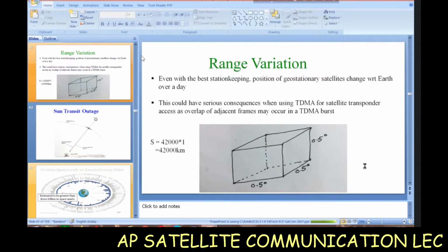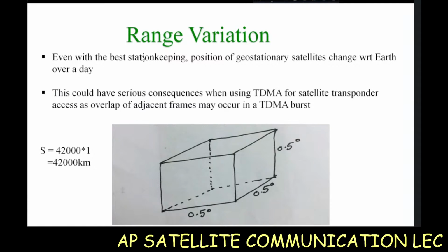So that tells us the kind of separation, but from the perspective of the Earth, when pointing your antenna towards the satellite, you can understand and appreciate the fact that it has to be very sharp and very pinpointed. Otherwise, instead of pointing towards a desired satellite, your antenna may be pointing towards some other satellite. So nowadays there is an international convention, or I should say regulation, that the movement of a geostationary satellite has to be limited within a cube, which is 0.5 degree on either side.